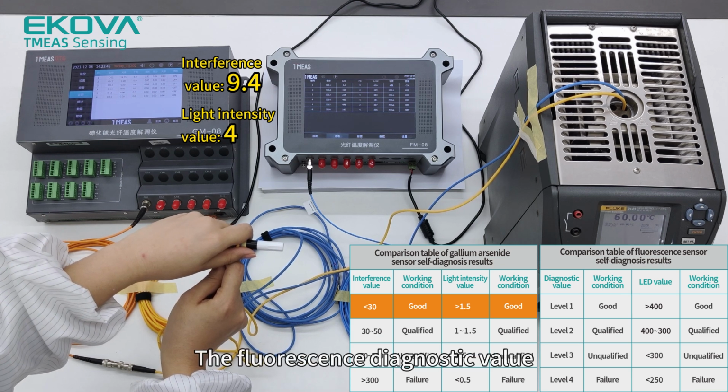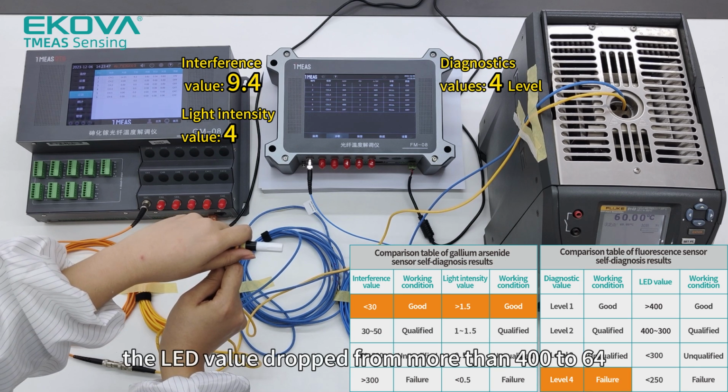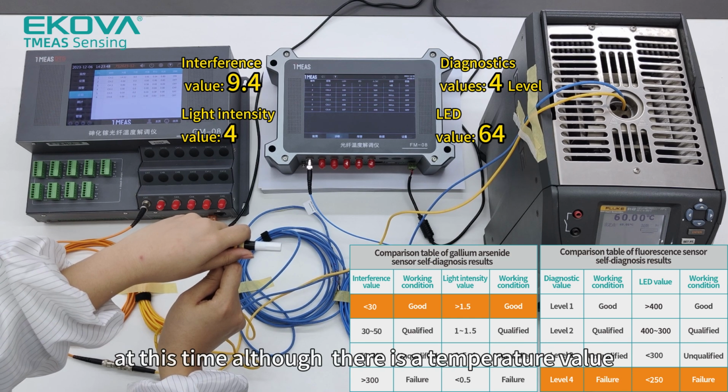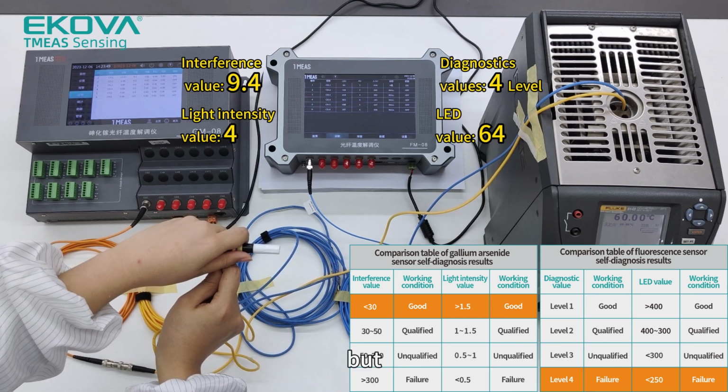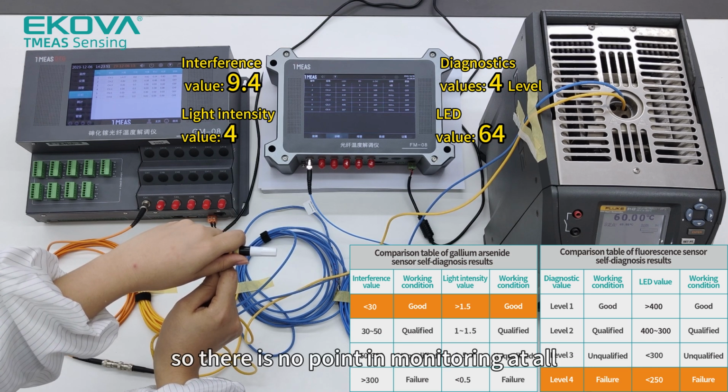The fluorescence diagnostic value is still at the failure level. The LED value dropped from more than 400 to 64, indicating that the light signal received by the host has become very weak. At this time, although there is a temperature value, it may stop showing the temperature at any time, so there is no point in monitoring at all.